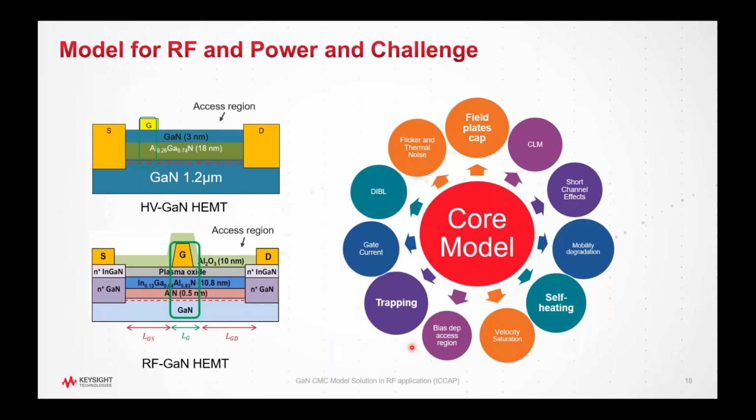And so in general, these two models cover all of this stuff, like the short channel effect, the self-heating, and velocity saturation. You might also refer to all the papers I mentioned in the slides. They have all these calculations included. And if you are using power devices, which is not covered in today's topic, then you will maybe consider the field plate. And these two models also talk about how you put these field plate models inside the equation and so on.